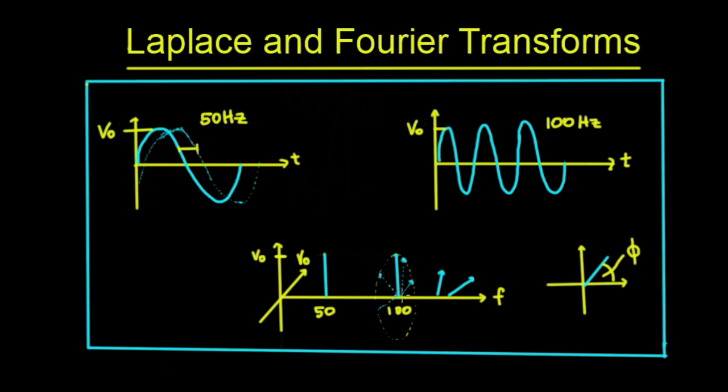If you take this axis here as your 0 degrees, then we would go around 90, 180, 270, then 360 would be all the way around. You can imagine this little phasor, if we call it that, rotating around this axis at 100 times a second, or at 50 times a second.